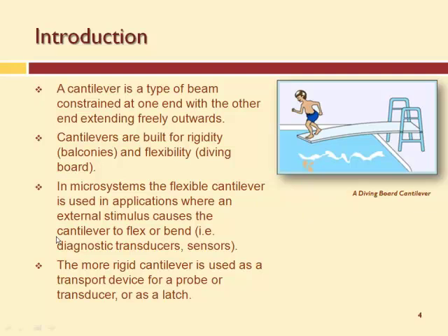The more rigid a cantilever is, the better it can be used for other applications like transport devices or for a probe. If it's not too loose or too flexible, you can use it for other things, or even a micro latch. People have used cantilevers for latches on micro machines. So you move something into place and it snaps into place.